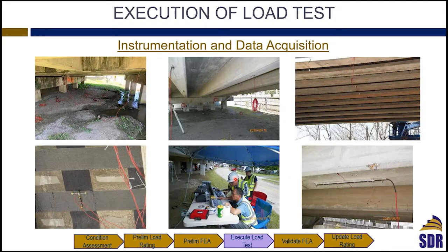Just to give you an idea, we go in the field and we start instrumenting our concrete spans or slab spans or steel. Sometimes we do the same thing for steel bridges, either swing spans or fixed spans, steel beams. We are typically measuring strains and deformation, which could be for concrete or steel. Those pictures give you an overview of the instrumentation we apply, and this is a picture showing members of the team, Dr. John Gates, and the members of our team sitting in the field to take the measurements while the truck is moving on the bridge.